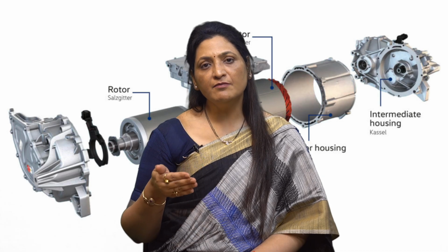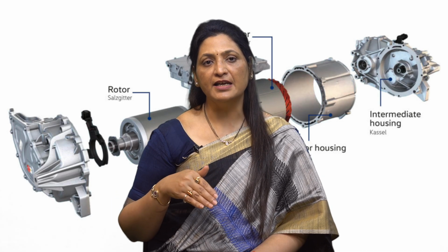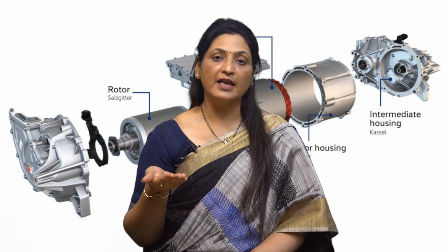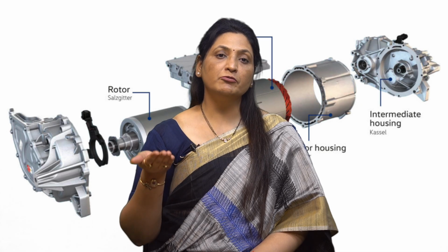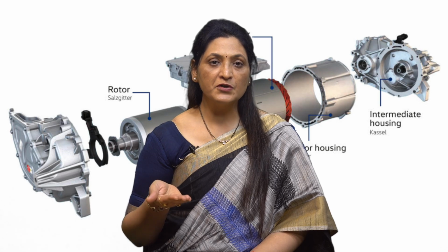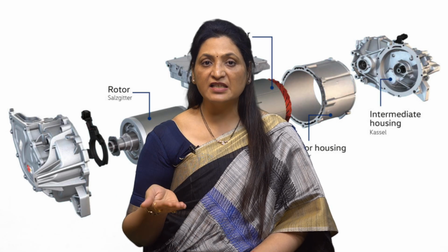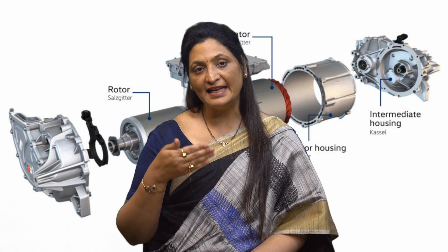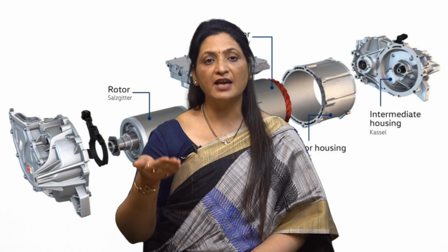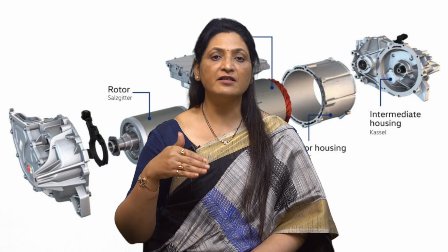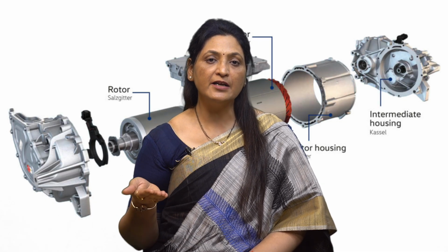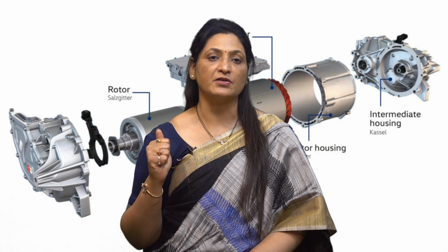The rating of an electrical machine indicates its load capacity limited by the considerations of temperature rise. According to ISI specifications, three kinds of ratings are generally specified. The first one is a continuous rating. It is the maximum load which the motor is capable of delivering continuously for an indefinite period without the temperature exceeding the specified limits, and it is also capable of undertaking 25% overload for a period exceeding 2 hours under the same conditions.